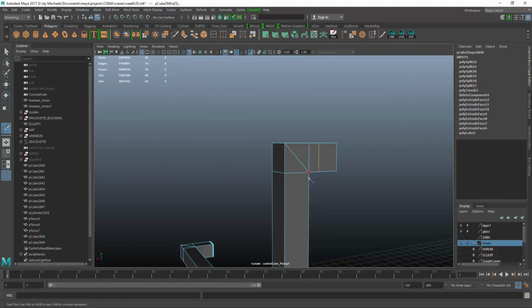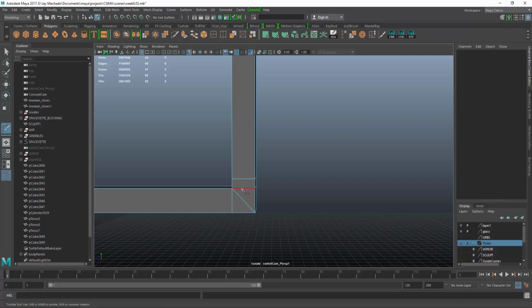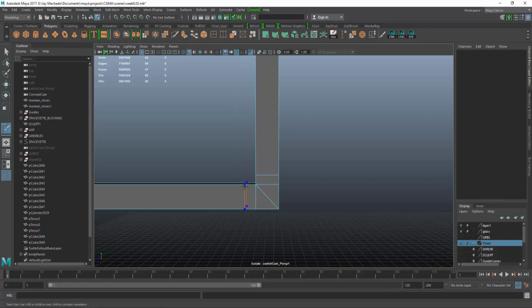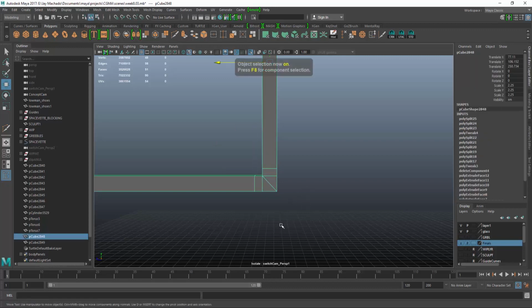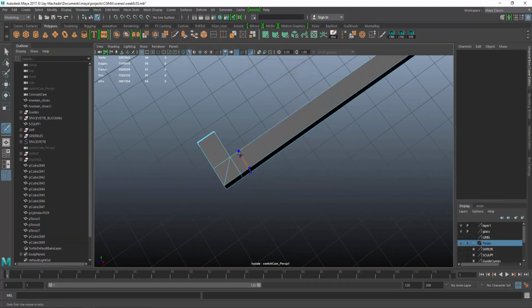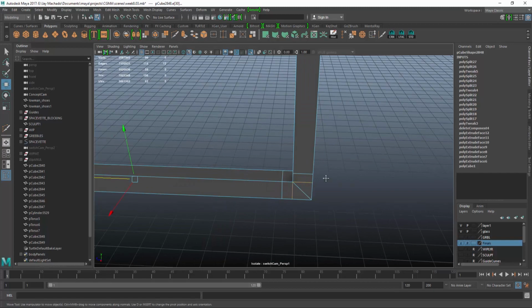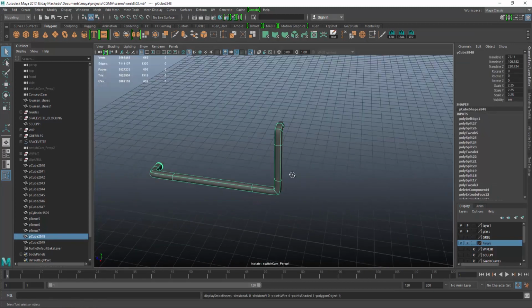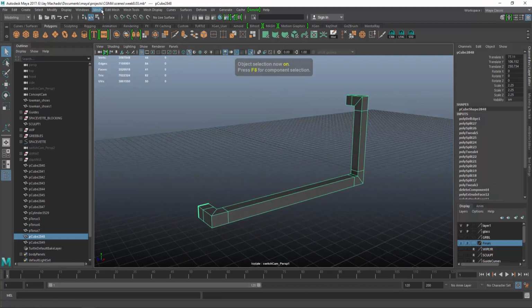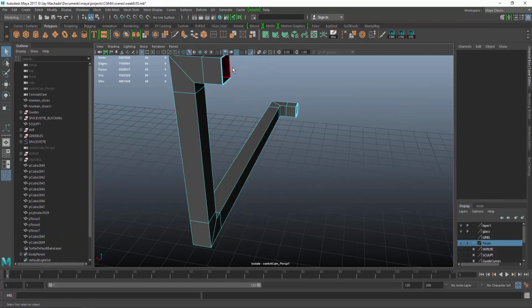And now let me drop in some edge loops here to support that curve that's going to be there. And I'm really eyeballing this as well, but I'm trying to make this edge ring kind of half the distance of the 2.25 we've done. And I like to maintain those square edges because it helps the supporting edge loops to remain flat. So now I'm going to run my smooth. Oops. So I want to delete this face before I run my smooth.